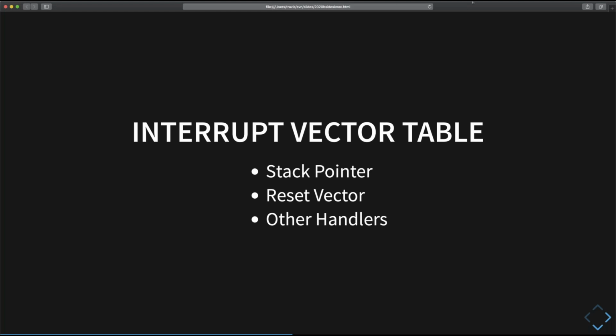That'll work. So the interrupt vector table begins at the very beginning of an ARM firmware image. When you get a firmware image, you don't get a .exe file or an ELF file like you would in Windows or in Linux. Instead, you very often get just a blob of bytes. And you need to figure out where those bytes need to be loaded. And you also need to figure out inside of memory where the basic functions are.